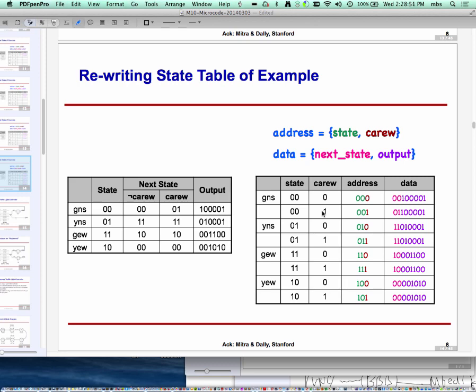Does that mean that, could you just have, instead of having only one bit for car east-west, 2 bits for car east-west? Yeah, let's say I were to do this example with car east-west and the left turn sensor. In that case, for each state, I would have 2 bits of state here, and then 2 bits of input, which means 4 combinations. So for each state, I would need 4 entries in that memory table. Whereas with the whole branching stuff, I don't need to have that.